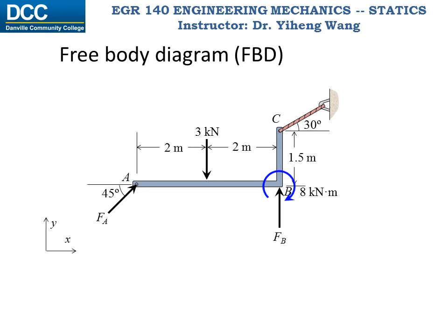Lastly, the cable at point C allows all motions except for when the member wants to move away. Therefore, the force of the cable is a tension force that pulls the member. Keep in mind that the force associated with the cable support is always a tension force that pulls. You can imagine trying to use a cable to push. Now, the free body diagram is complete. We have 3 unknowns, Fa, Fb, and Tc. And we can write the 3 equilibrium equations and solve for all of them.